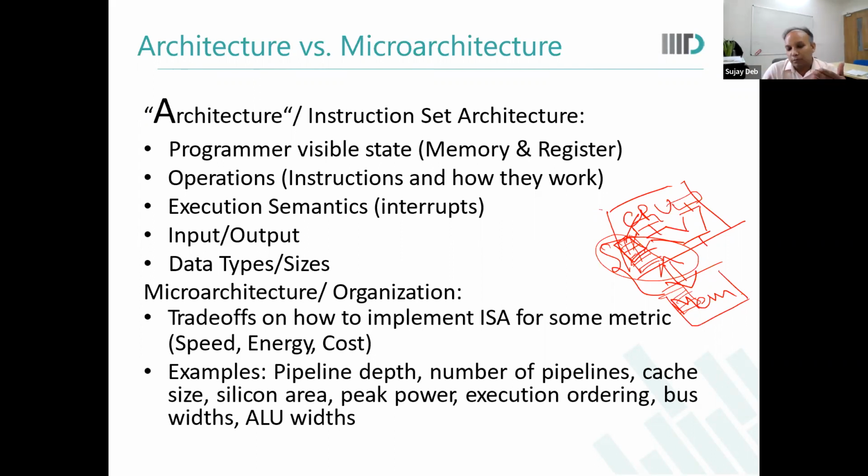physically build maybe, let's say, 2 to the power 10 bytes of memory physically and map it virtually to all the 2 to the power 32 addresses. So basically there will be a step where the virtual to physical mapping will be done. The programmer may assume that, okay, I have 2 to the power 32 memory spaces, but I have physically 2 to the power 10 only, and I'll be intelligently mapping them in and out so that the programmer will not know that the hardware is much smaller.